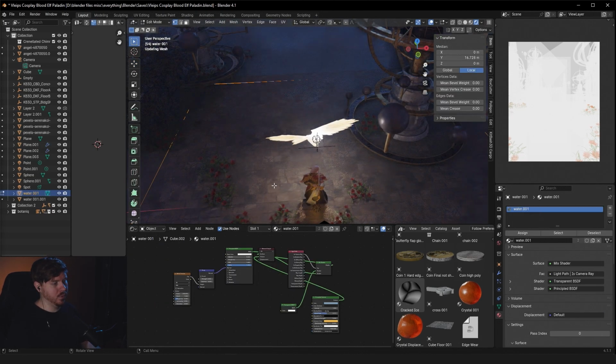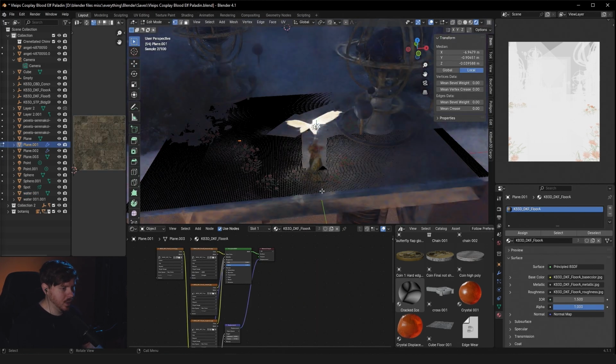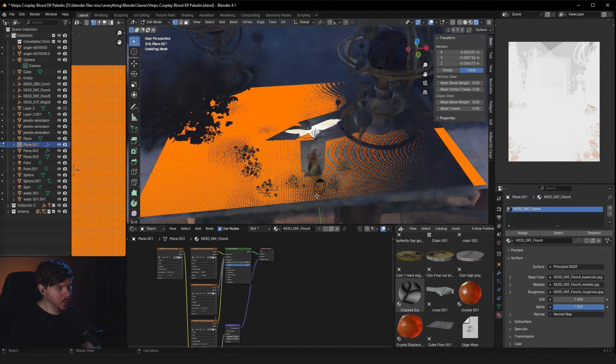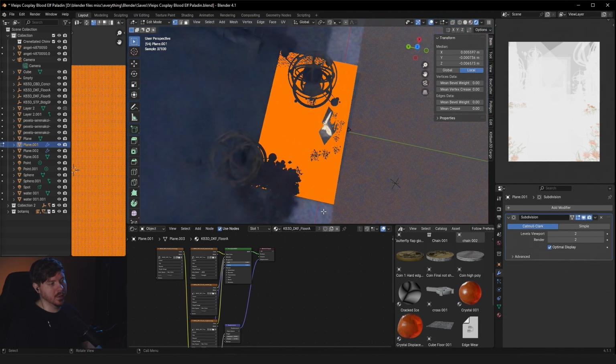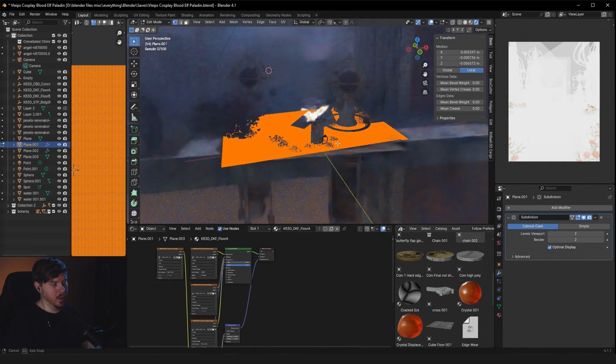Also, for the floor, you have to have a lot of mesh going on so it can have the detail in there. So if I press Tab, you guys can see I subdivided this. So if you press A, right click, and you subdivide, I did that by 100, and then I did it one more time. So it's a lot. So that can become really, really heavy. So I just tried to do enough to where you couldn't see detail anymore, but not too much to where it's going to mess up the speed of my PC.